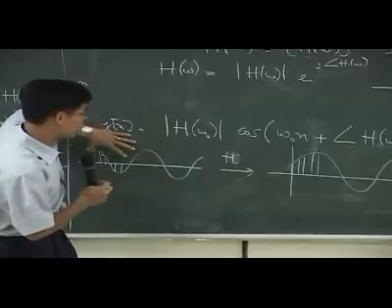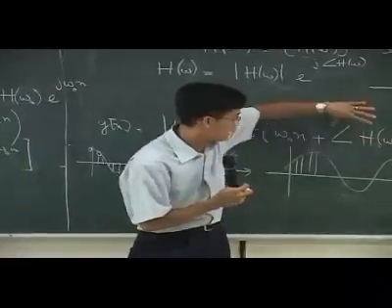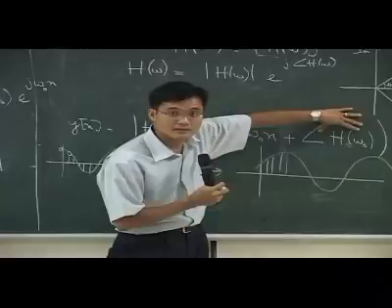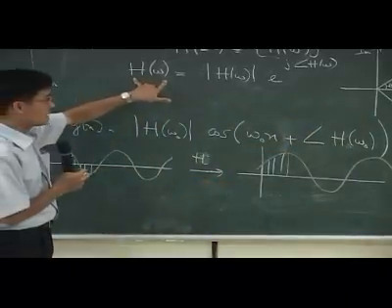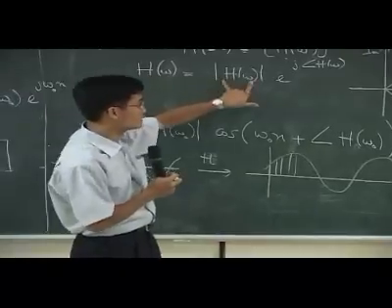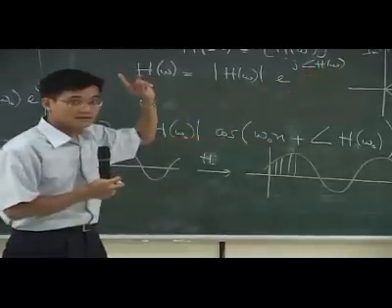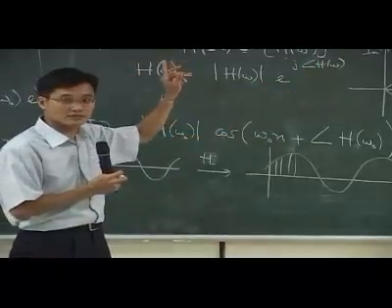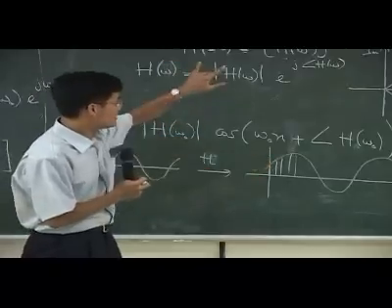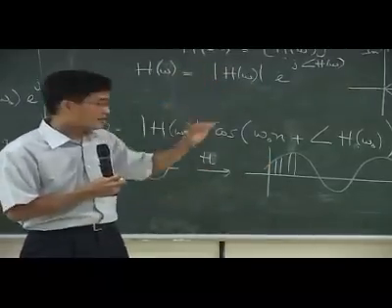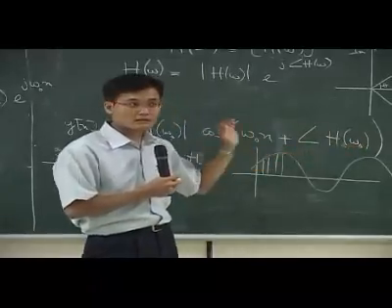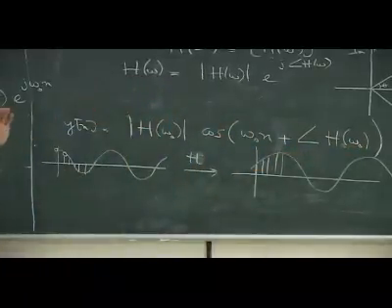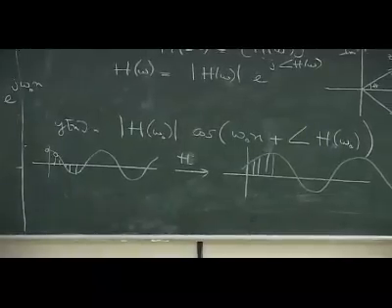Second, this gets shifted by the phase. So a filter, when I design it, has a complex number with a magnitude and phase, and they do two different things to the signal at the output. The magnitude magnifies and the phase delays. So when you look at the filter, you can see what each component does.